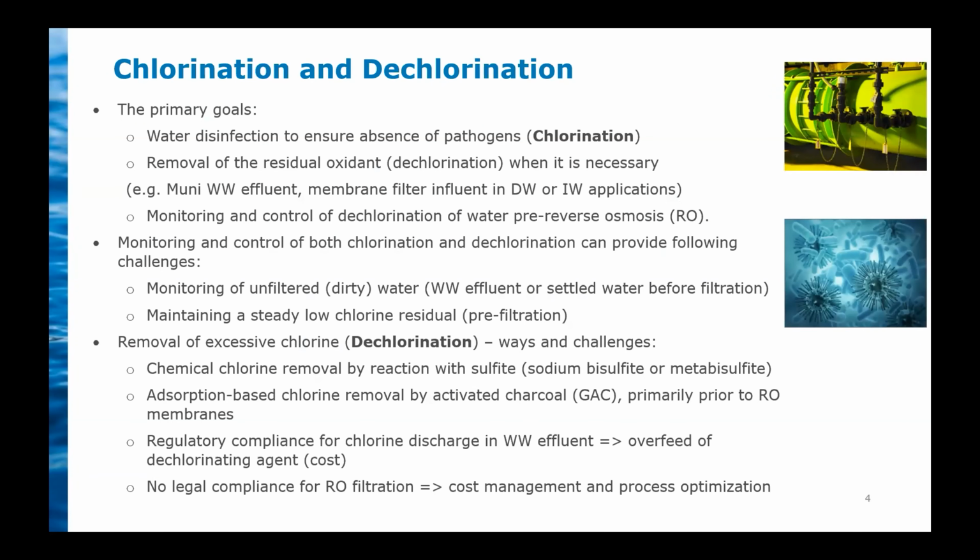And in case chlorine is used for RO feed, the monitoring and control of chlorination and dechlorination is the primary goal. Here, the concern is that chlorine will damage the membranes, shortening their lifetime and causing increased salt passage.